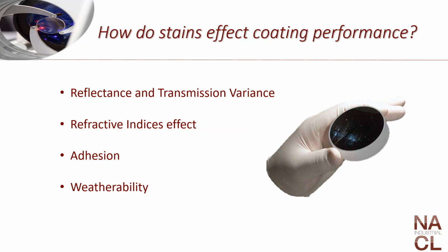Sometimes this is easily spotted if there is slight adhesion failure, as just a localized spot of adhesion loss. Whereas if there is catastrophic failure, you can usually chalk that up to some issue with the run or a heavy amount of contamination that just was not removed prior to coating.